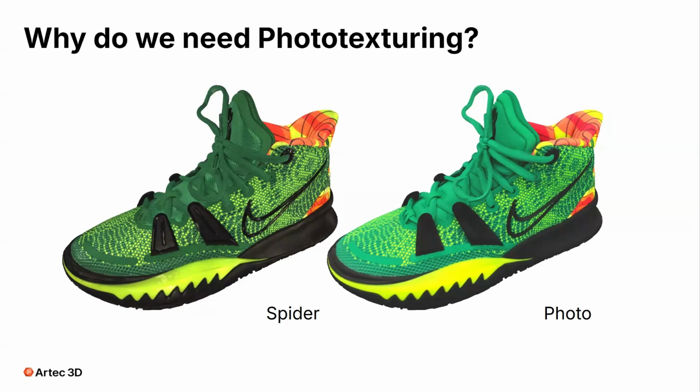If you take a closer look, you will see that glossy surfaces on the Spider scan have some reflections baked into the texture, which is not ideally what we would want for the production-ready model. So it's best to avoid it. And one way to do this is to use the photo texturing.